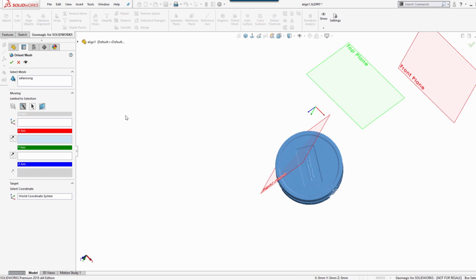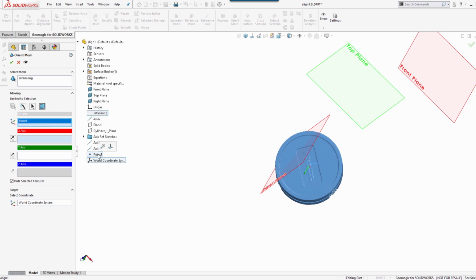Okay, so with this one, once you have your reference stuff, I could be live selecting those faces here, but I like to do them beforehand. So I have reference geometry. My first box is my origin. Because I have a point, I've got my point, and now I'm going to do an X and a Y, or an X and a Z, or even a Y and Z. I don't need four references here, right? If I have my center and two of my axes, it will force the other one to be exactly what it needs to be in the long run anyhow.